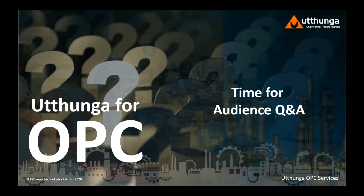So if you are creating a process automation device, for example, a flow meter, then on the flow meter you can have an OPC UA server whose information model is defined as per the PADIM specification. So in other words, PADIM is one standardized information model from the OPC UA Foundation and FieldComm Group. I hope that answers your question.